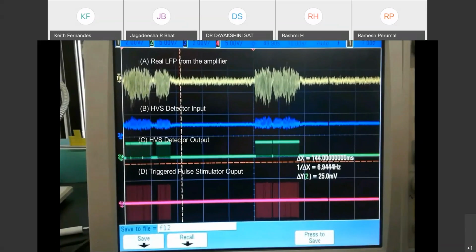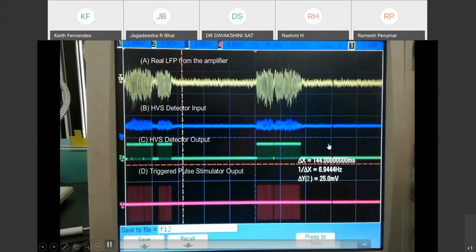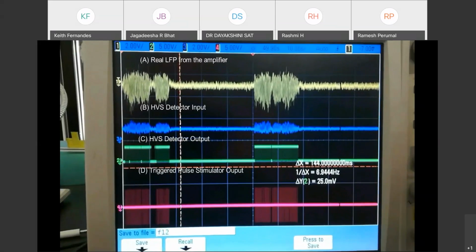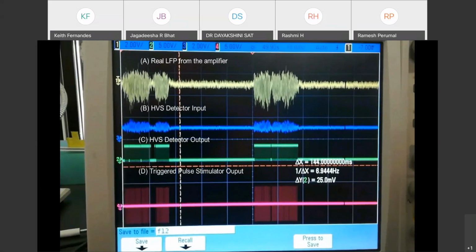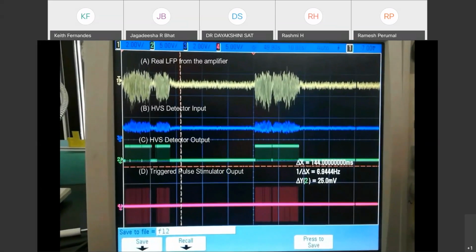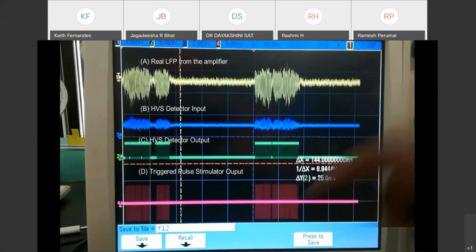You can describe this technique as improving the temporal resolution of the Fourier transform by using a predictive model. It predicts the signal. If we apply the Fourier transform with the window length of 1, just directly without any predictive model, the result will be very poor due to the lower temporal resolution.